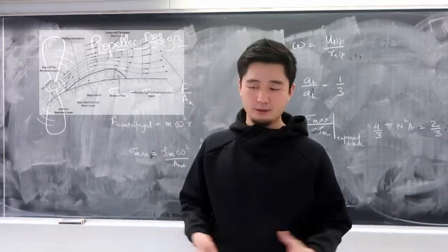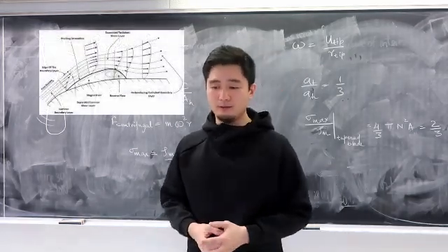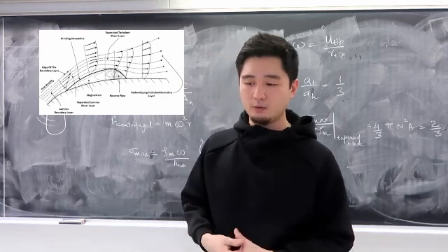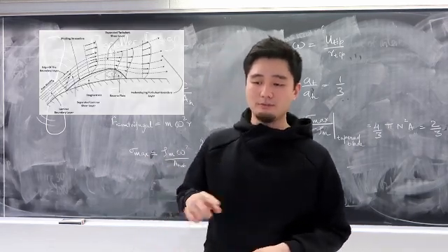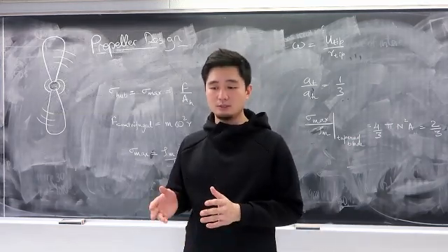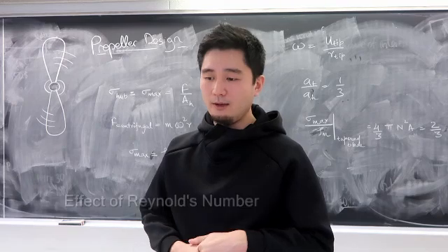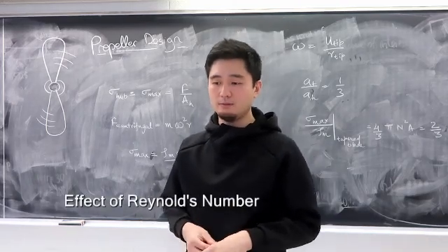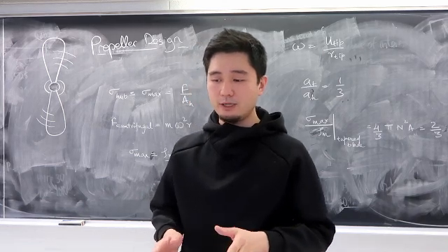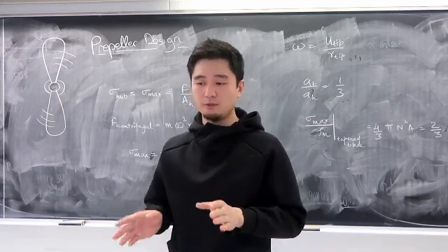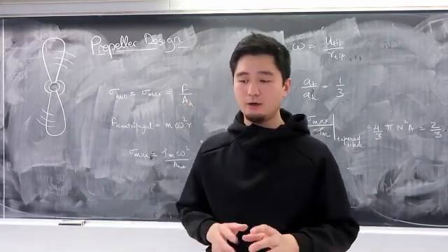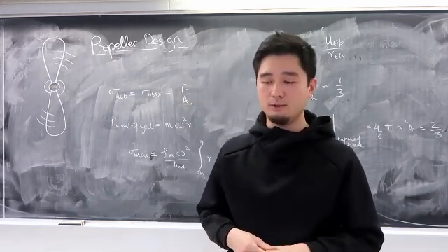So as we know from class, if the low Reynolds number occurs, then there's less inertia in the flow. There would be separation bubbles that can form just above the surface. So the separation bubble causes an increase in drag and a decrease in lift. So with the test motor spinning at 5,000 RPM, which is relatively high for a small propeller, this would actually enable the larger portion of the propeller to experience a higher Reynolds number. But the center hub is unavoidable for low Reynolds number.